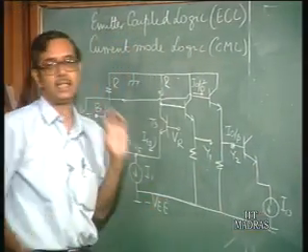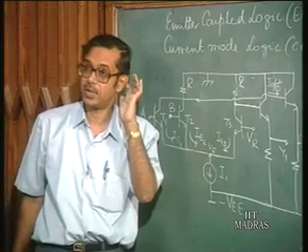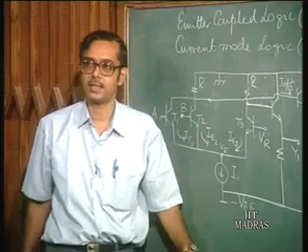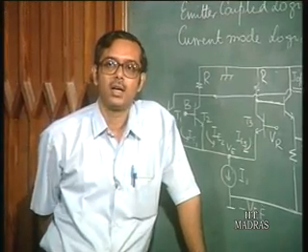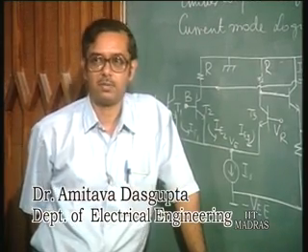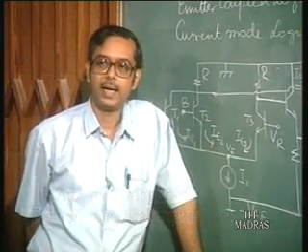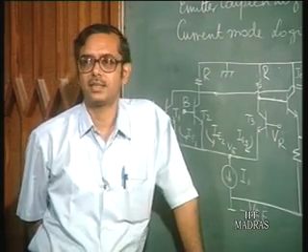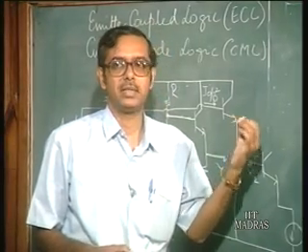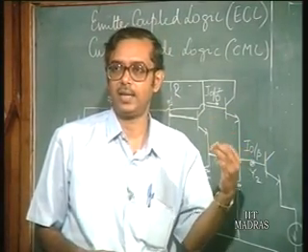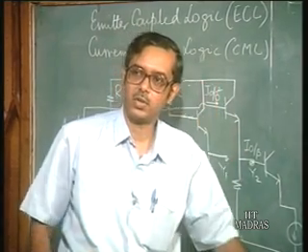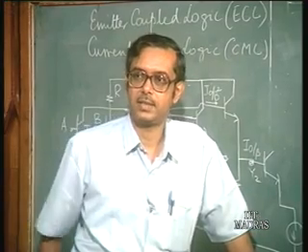See, the ECL gate, like all high speed gates, we have already discussed, has some problem due to noise. All high speed gates suffer problems due to noise because of the very fast switching, and large amounts of current are switched from one branch to the other. Because there are some inductances in the circuit which normally you tend to neglect, if your current is changing, dI/dt is very high. And if there is an inductance, you get certain voltages. L dI/dt is the voltage.